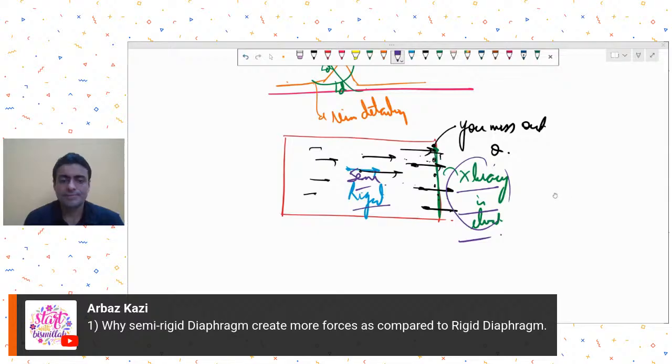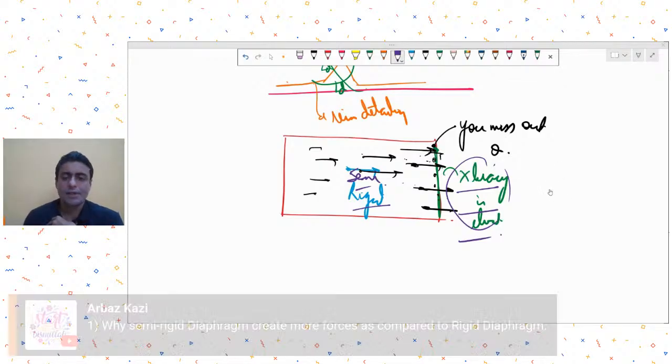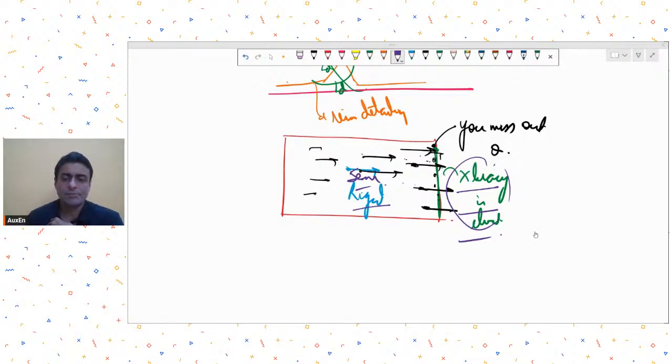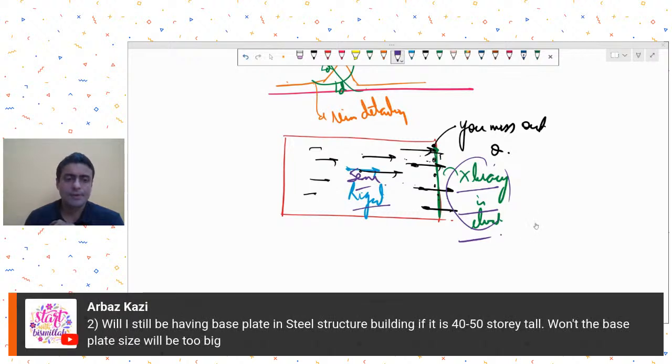So therefore, this thing happens, and that is why we need to be careful under which case we should assign the rigid diaphragm assignment to your slabs. Okay.